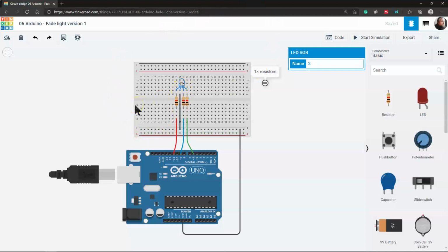And in the physical ones, if you have the Freenove kits, they have an RGB LED that has a common anode. Now, you may be wondering, how do I tell the difference? Well, if you hook it up and you get the wrong colors and nothing's working, good chance you probably need to switch around how you set things up, testing it out, or check what you buy. So again, for the simulator, you're going to be working with a similar circuit and have the fading, with an RGB that says common cathode. If you have the Freenove kits, you will have an RGB that has the anode, and in the physical work videos I go through that.